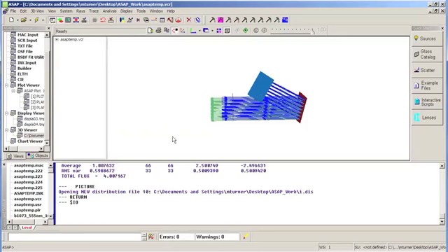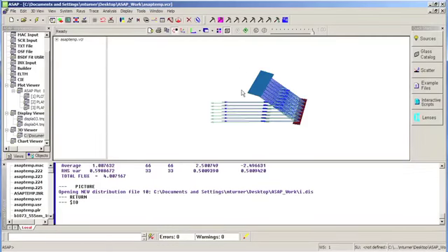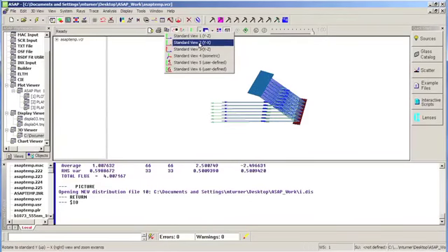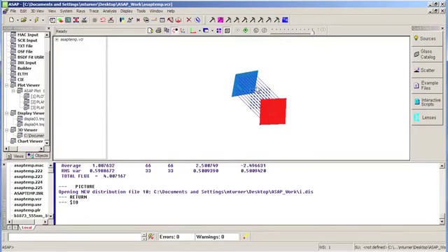The problem is, when we defined a standard window, it was perpendicular to the z-axis. So in this case, if we click right here, we're talking about a plane that is oriented in this fashion. Unfortunately, our mirror is positioned like this, and if you'll notice, if we look at this in the global coordinate system in the XY plane, you see exactly the ray pattern that we saw on the spot distribution plot.